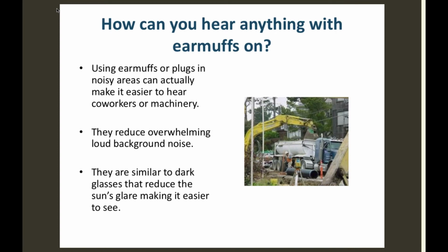And OSHA, I'm sure they've done research on this, and they figure, you guys take statistics? How many of you have taken statistics? You talk about confidence interval, right? Basically you want that 95% certainty that you're going to protect 95% of the workers at the level that you think you are. If it was really going to be 100%, then you'd take this noise reduction rating of 29 and say it's 1 decibel, which is ridiculous, because then they wouldn't even be worth wearing. You wouldn't be able to assume any reduction. So this is a formula they've calculated would protect the majority of workers at that level, at 11.5 decibel reduction.